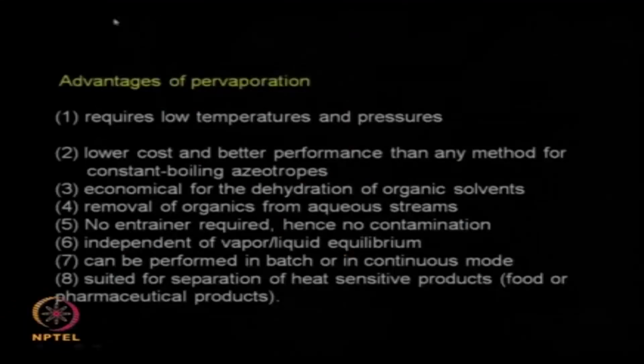It will absorb all the water present in a solvent, and then you will do a filtration. Now this silica gel or alumina will contain water, so you may have to take it to a heater and heat it, so the water gets vaporized, the silica gel is again available, you can take it back again for adsorption. So you see there are so many extra steps, it is going to add to the cost, whereas pervaporation